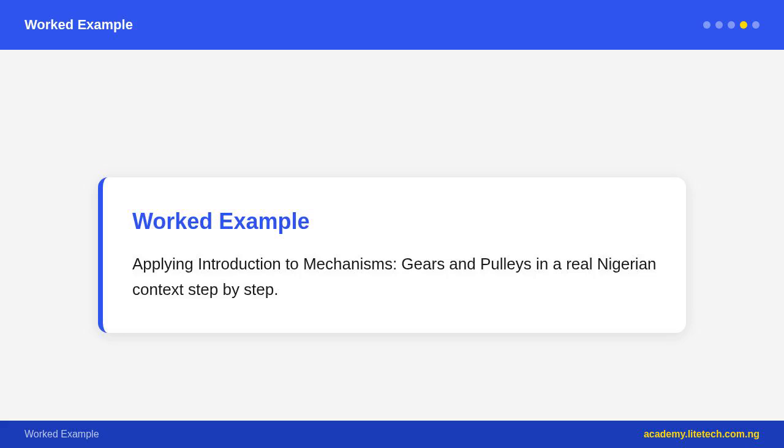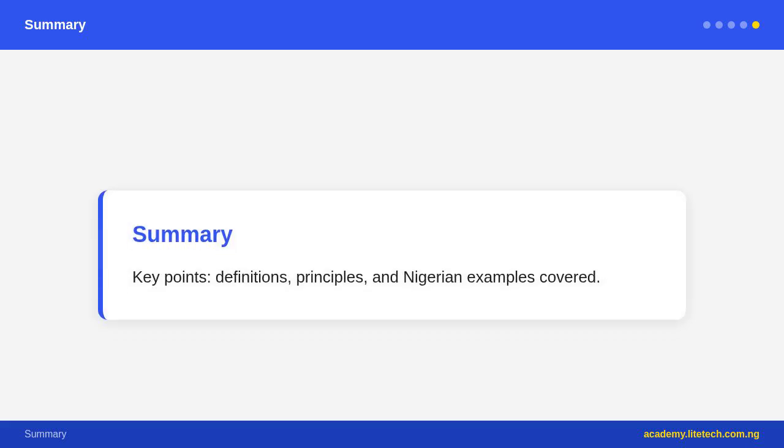A block and tackle is a system of multiple pulleys, some fixed, some movable, working together. The more pulleys in the system, the greater the mechanical advantage. If you have a block and tackle with 4 rope sections supporting the load, the mechanical advantage is 4. You apply 1/4 of the load's weight but must pull the rope 4 times the distance the load is lifted.